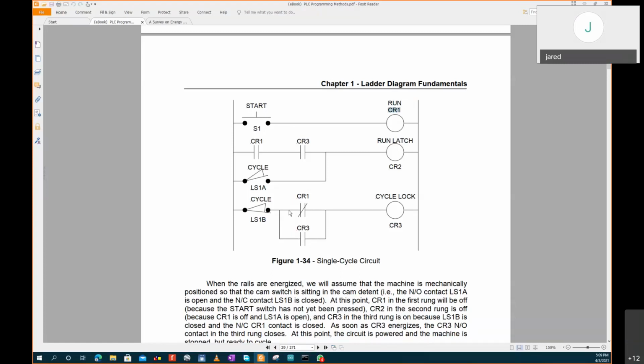takes out, but immediately, as you press this one, CR1 turns on instantaneously. Okay, you press start, it turns on CR1. There is a circuit before it goes off, the power goes on, and the CR3 coil holds this circuit locked. Okay, so this is just a brief explanation.